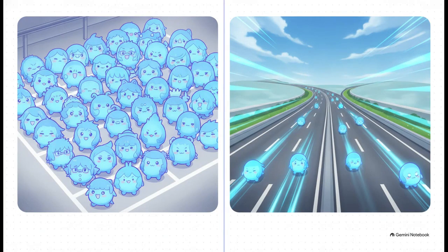Within this theory, there are two primary bands we really care about. Think of the valence band kind of like a crowded parking lot where electrons are securely bound to their atoms. At absolute zero temperature, this is where they're all stuck. But just above that is the conduction band, which is essentially an open highway. If those parked electrons can somehow get up into this vacant band, they are finally free to accelerate and zip across the material, carrying an electrical current.